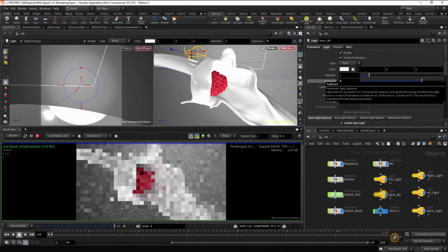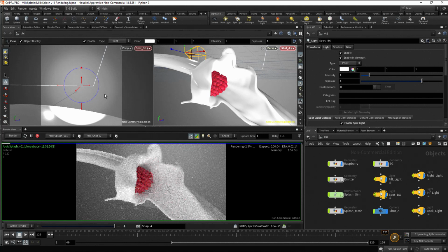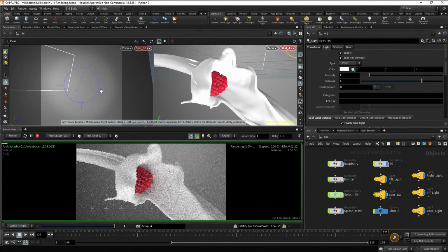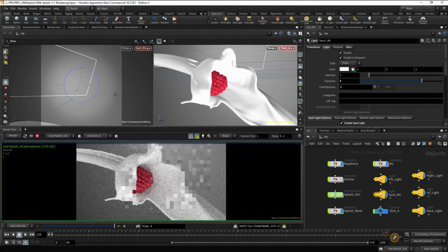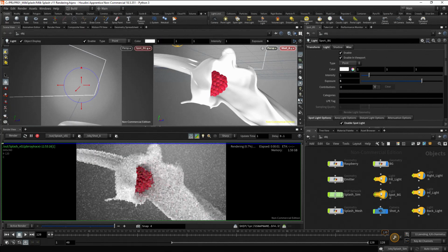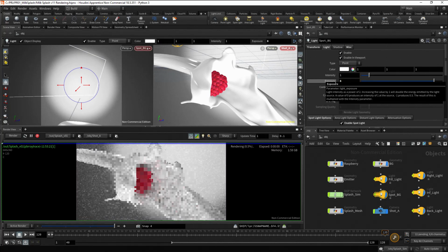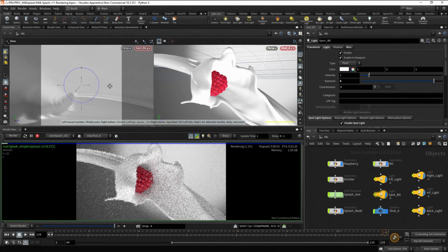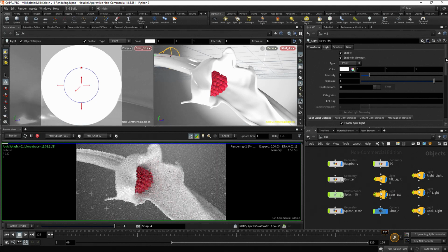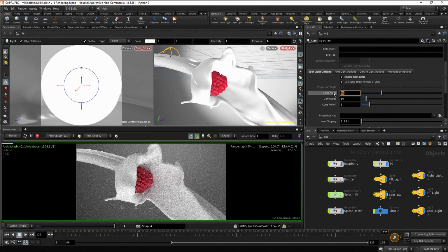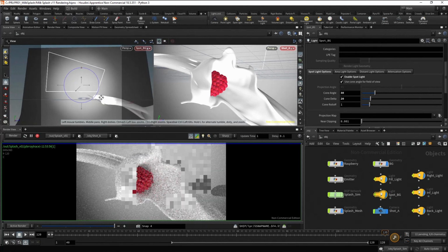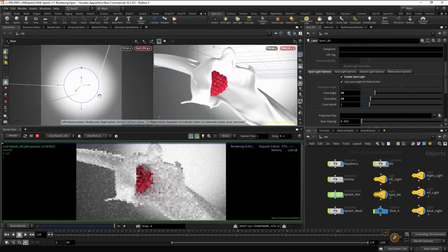Adjust the exposure. Let's make some additional adjustments. Adjust the exposure. Now, to control the spotlight angle and the penumbra, go to the spotlight options and start changing the cone angle and also the penumbra or cone delta. Continue adjusting the position and the spotlight's parameters.